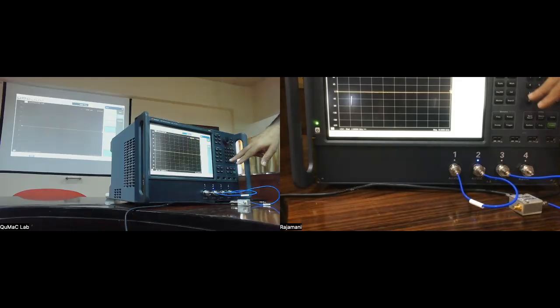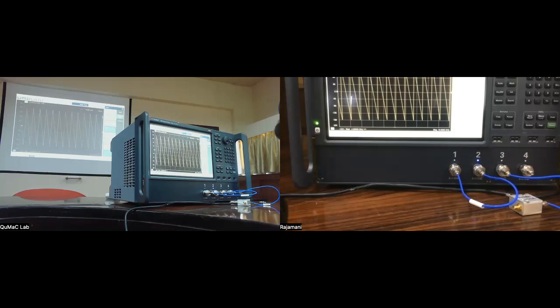So let me actually put this back to reset this so that you can see what we were having about it. I'm just doing a transformation inside to get rid of this phase change, because this phase change is not giving me any information. Whereas the device I'm trying to study could have some other interesting phase relationship, which I might need to verify. So for example, we had talked about LC resonators in one of the early classes. So that has this 180-degree phase shift as you go through resonance.